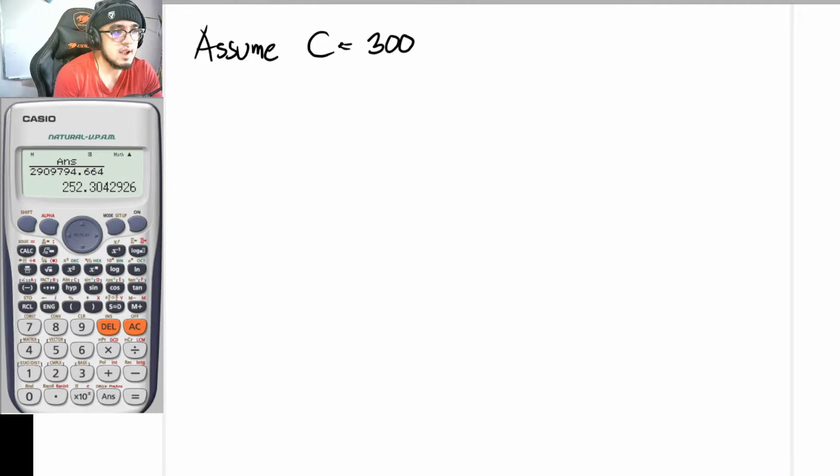Okay, so let's try. If C is equal to 300, our Fs prime is equal to 600 times (300 minus D prime, so 75) divided by C. So I would just be writing the equation here: C minus D prime divided by C.